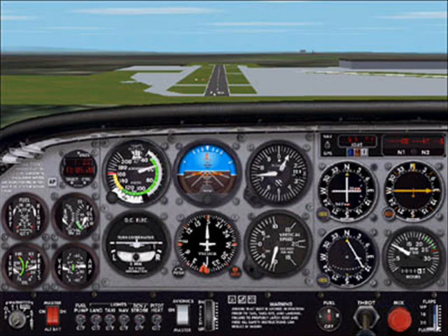So why use flaps? They allow you to touch down at a slower speed, which means the airplane needs to dissipate less energy while stopping. Additionally, flaps come in handy when you're too high on approaches. They also are useful when landing over an obstacle, or when landing on a short runway.